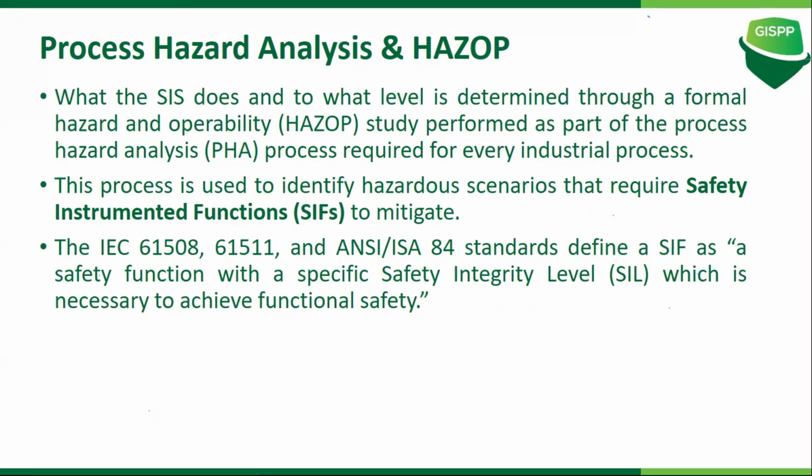For that, we have safety instrumented functions. Those are the processes that safeguard the values from the HAZOP. They come from IEC 61508, 61511, and ISA standard 84, which define the basic safety integrity level that has to be achieved.